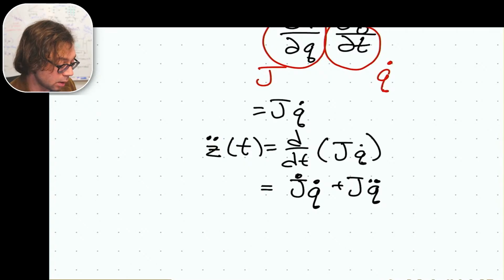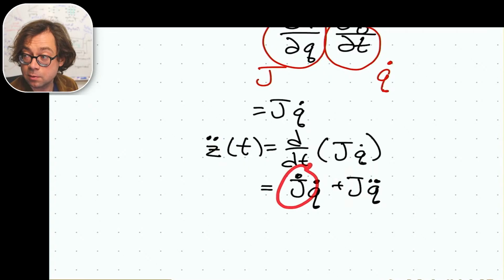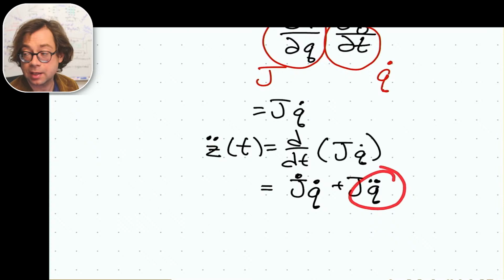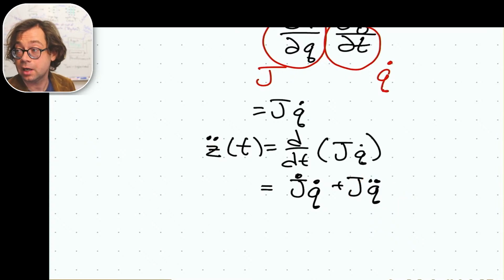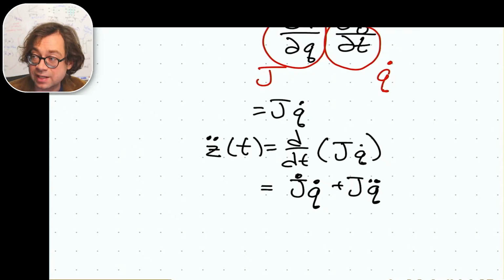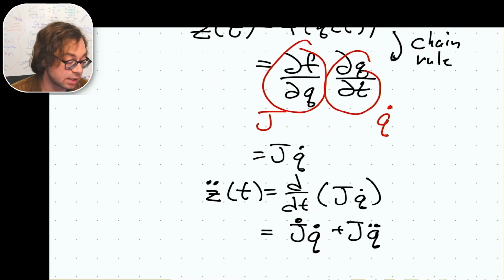So if we compute our Jacobian and we compute our time derivative of our Jacobian, well, guess what? That's z double dot of t. Okay, we can get that by multiplying by q dot. That's going to be an input to our function. And q double dot, that's one of our decision variables. Done. Okay, so let's go into the code and try to set up these particular quantities into the symbolic toolbox.